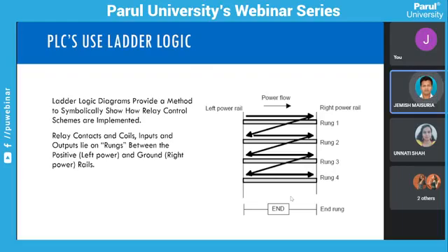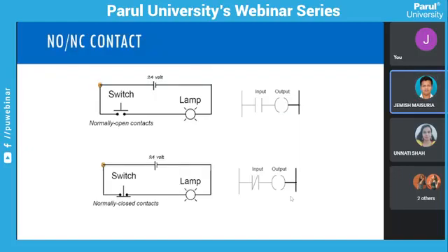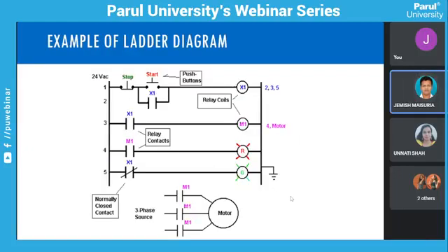One example of a ladder diagram looks something like this. There is a soft switch, a start switch. X1, X2, X3 are the sensors, and the circles, X1 and M1, are your coils, relay coils or actuators. According to those switches, these particular devices will be operated.